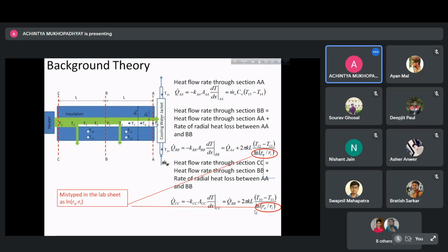There will be heat transfer but there will be a negligible temperature drop. Heat transfer is not negligible. We are considering temperature gradient just like what you did in the fin analysis. You just remember what you did in the fin analysis. In the fin analysis also you considered a slender fin, that is the fin whose L/D ratio is much greater than 1. But there was heat loss from the side.